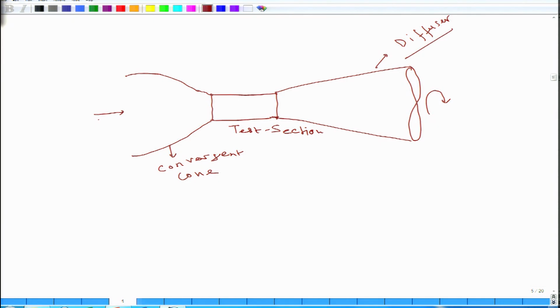Please understand, like computational fluid dynamics, in performing the experiment, the wind tunnel by definition is a simulation mechanism, that is the experimental simulation of the models, so that you can perform the measurements and claim the data, maintaining the similarity of the parameters, similarity of the flow situations, so that you can claim the data for the actual prototype, that is for the actual aircraft, worldwide.